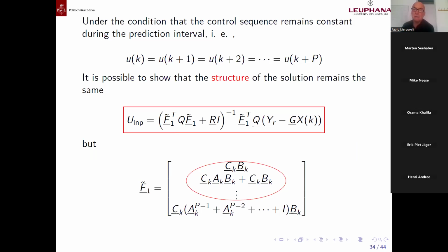If you think about possible variations, sometimes we are considering U constant. Why that? The reason for this hypothesis is practical: often we don't have a very long prediction horizon, and this means if in particular TS is very small, we can consider really just the first element.